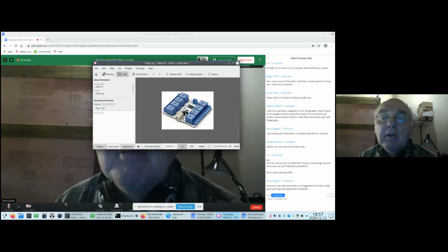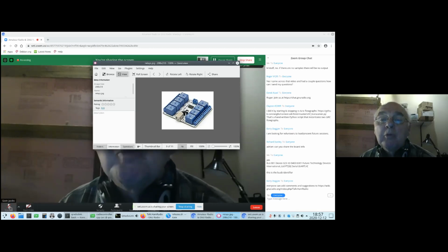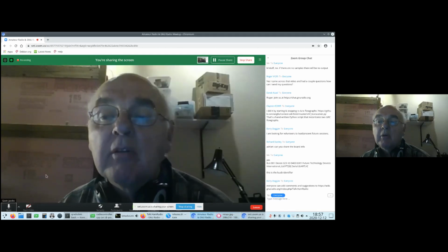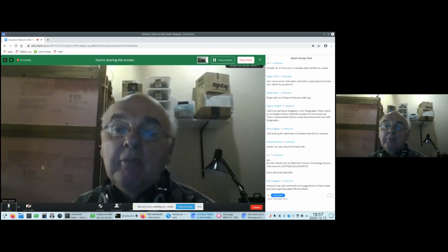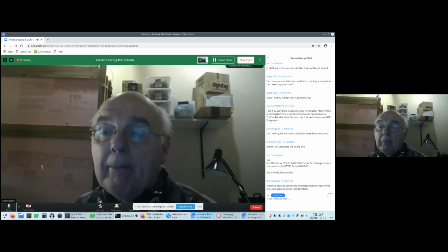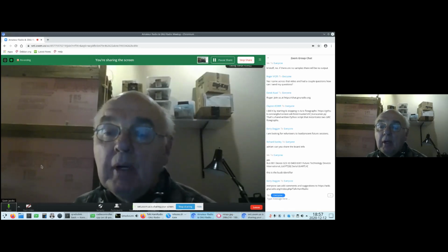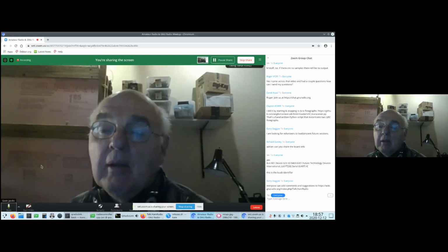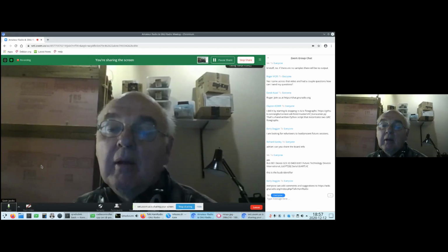Okay, yeah, that's pretty much what I thought it would be. So those relays, are they fast acting? Do they have good isolation? Those are the questions I would have if you're going to use them. These relays are meant for home automation, for switching 220 volts, so they can stand a huge amount of current and large voltage. They're pretty fast switching, I think. They take a couple of microseconds to switch.